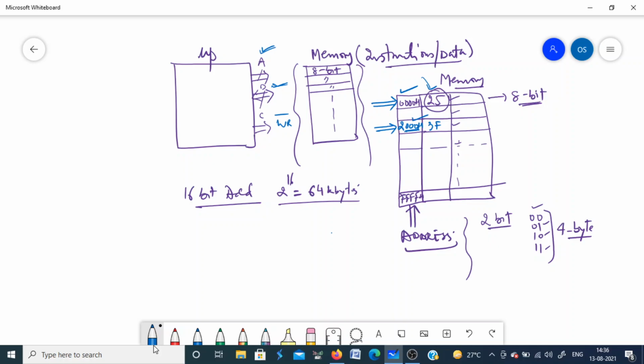Then what is next? Will you place the data on the data bus? No, because you have no information about the data. If you already knew what data you wanted to get, there would be no need for this read operation. Next, the processor will send another control signal, which is a read signal,